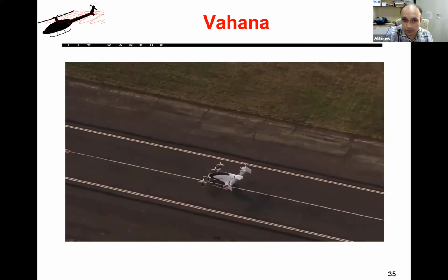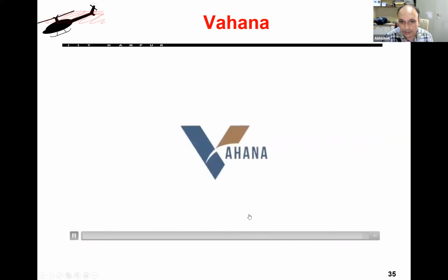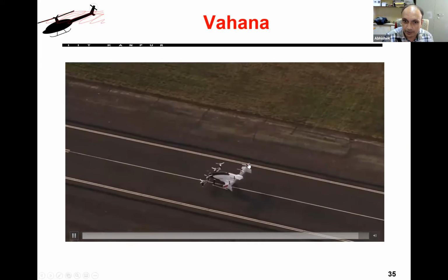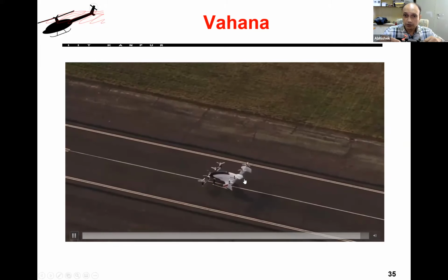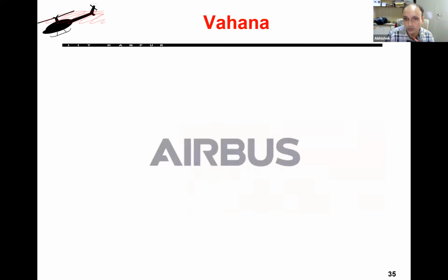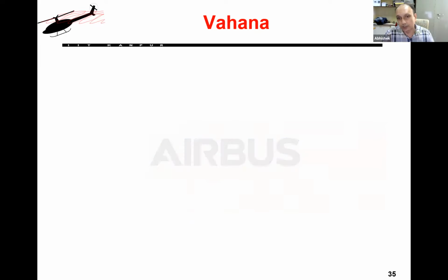By having propellers which are distributed across the whole wing. So you can see very clearly the entire wingspan is practically covered by these propellers. So what happens now? These propellers have a significant amount of downwash. And in the remaining lectures, we will actually see how to calculate this downwash. That is the flow which the rotor is inducing and pushing downwards.